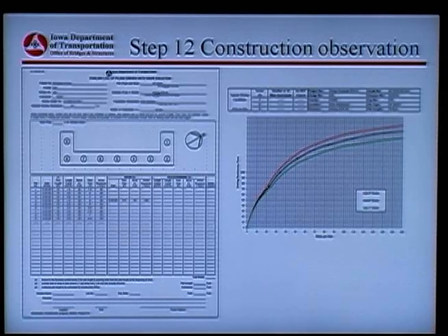The next columns over here have to do with if we have to retap it. So on this particular example, we had 30 blows per foot at a 7-foot stroke, or I guess it was a 7.5-foot stroke in here, if I'm looking at how it's interpolating between the two, and we got 88 tons of capacity.